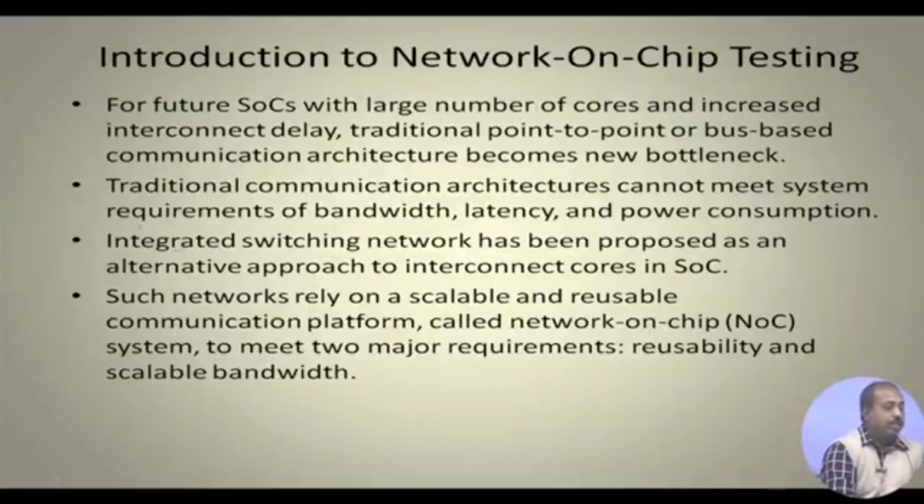So, for future SOCs with a large number of cores and increased interconnect delay, traditional point to point or bus based communication architecture becomes the new bottleneck. I have said that the bus cannot do parallel communication, more than one communication cannot be done simultaneously, and point to point means there are a large number of lines running through the chip.